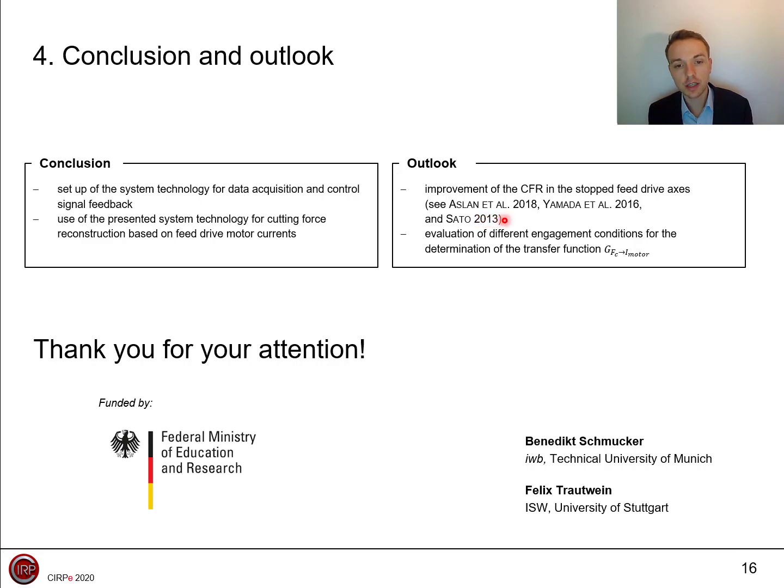It is also necessary to assess whether other engagement conditions, for example half or quarter immersion cuts, and other experimental strategies such as increasing spindle speeds, improve the determination of the transfer function. However, the system technology can not only be used for cutting force reconstruction, but further process monitoring, process control, and process optimization tasks can be implemented based on the presented system architecture.